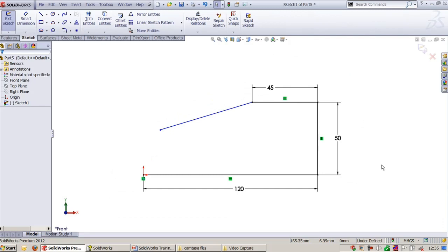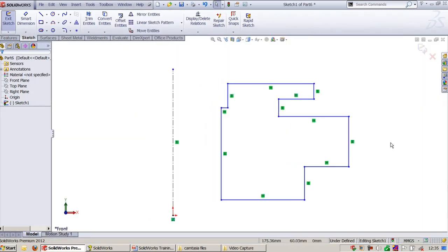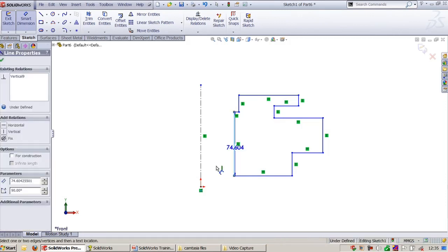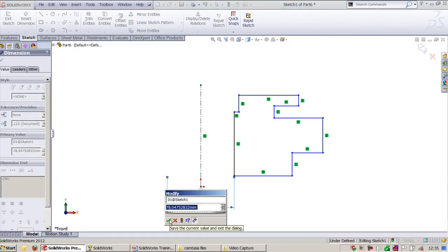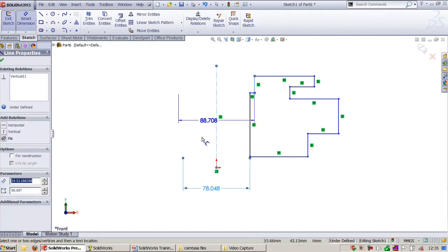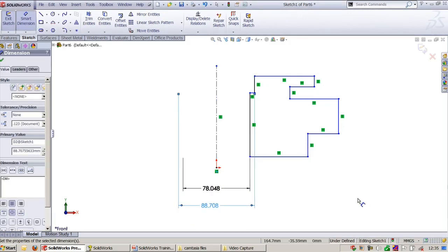The next one is doubled distance, which is one more interesting relation in SolidWorks. When you detail any revolve section, we create a diameter dimension represented in this way. How? Go to dimension, select this line segment and the center axis, and if I drive this, you will get this doubled distance. We normally use it for cylindrical geometries, and this we call doubled distance.